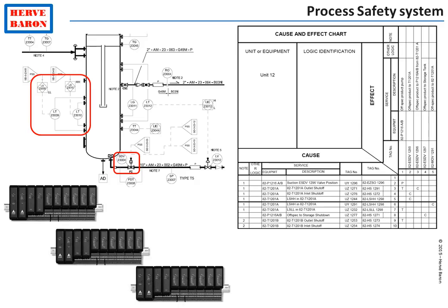As the process safety system performs safety functions, it requires a high level of reliability, and the corresponding controllers are either duplicated or triplicated, i.e., instead of one controller, there will be 3 controllers, so that if one fails, the other 2 will detect the failure and will take over and implement the action.